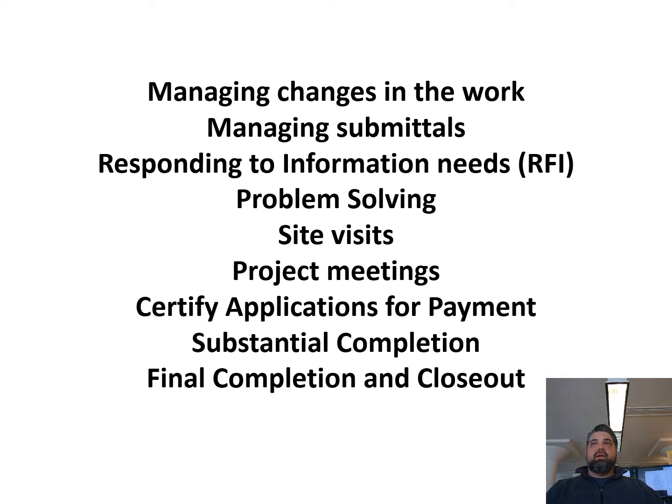So there may be areas where they have to touch up paint, or adjust a closer on a door, or they need to test and balance the HVAC, but the owner can use it, right? They can move in and they can use the building for its intended use. That is an important date because that's the date at which most warranties take effect, and is the date that will be used for that 12-month clock for the contractor's warranty.